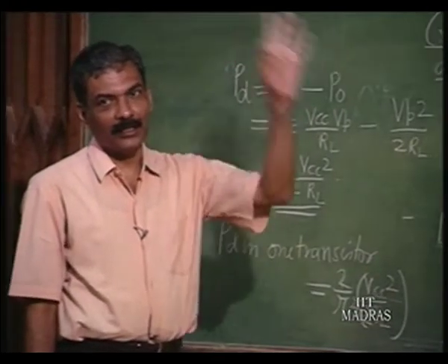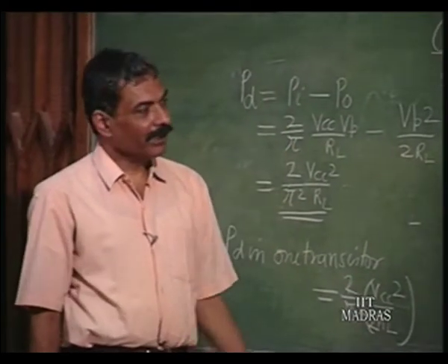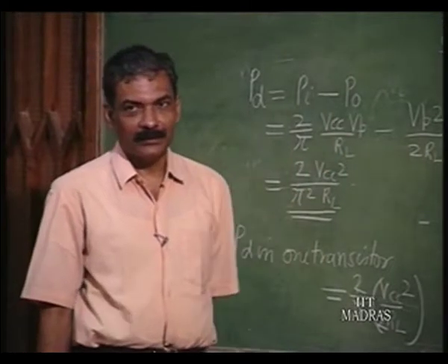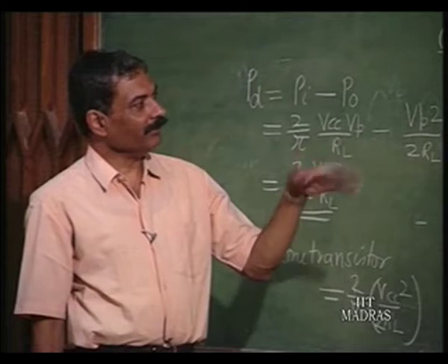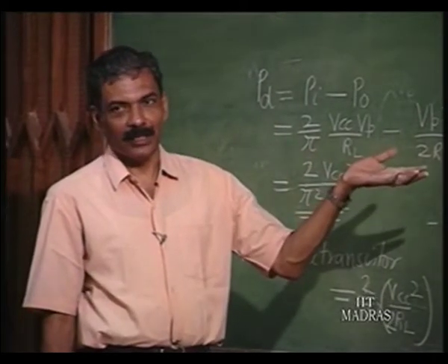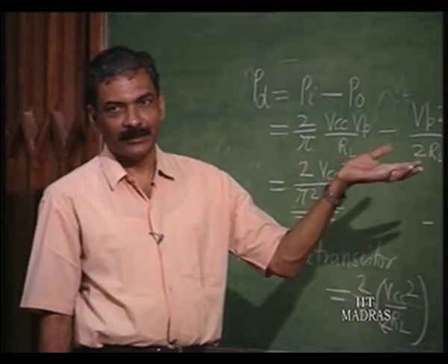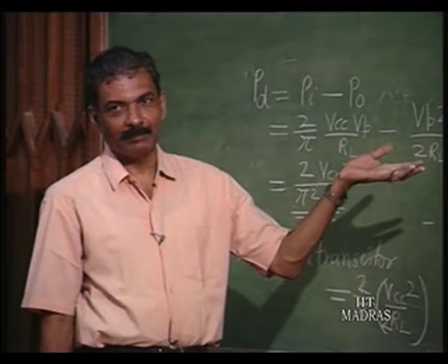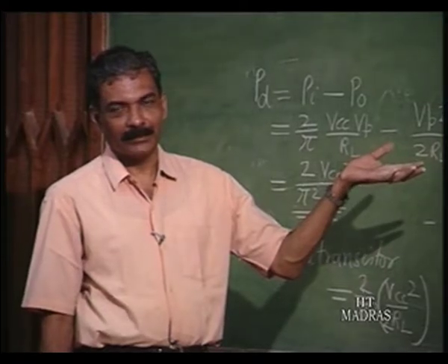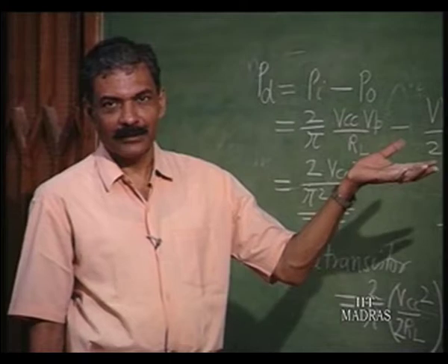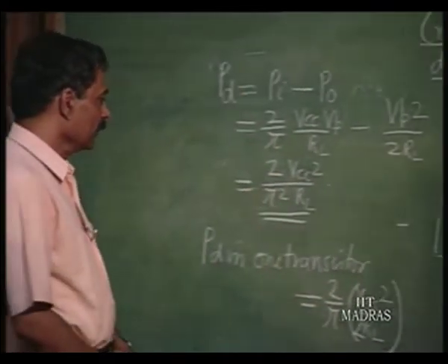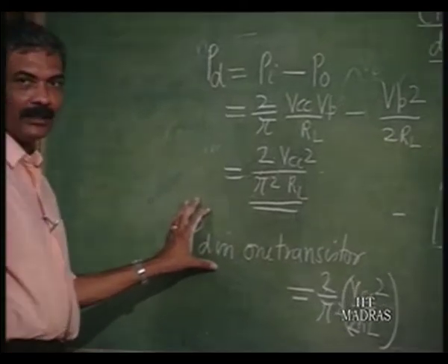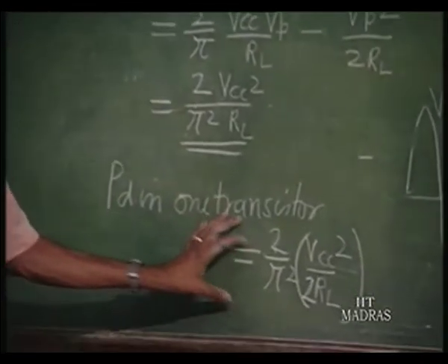Consider this earlier situation when we had output power of 10 watts, we had to have something like 20 watts for the maximum power dissipated in the transistors. Is that clear? So, this is the difference between class A power amplifier and class B power amplifier.